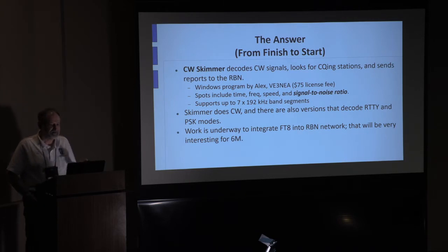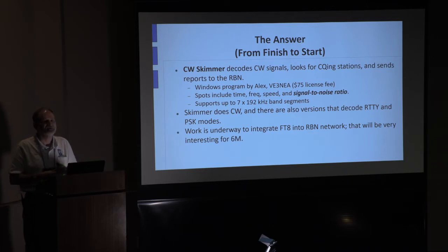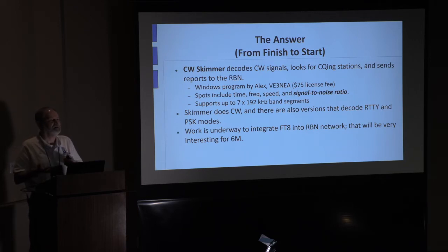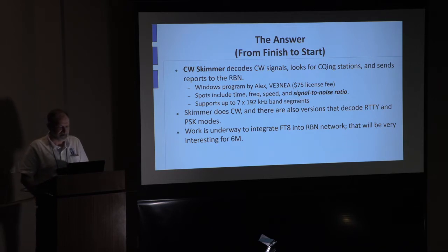So the magic of this is on the HF bands, there's a software called CW Skimmer that can look at a chunk of spectrum coming out of usually an SDR receiver, decode all the CW, pick out the interesting stuff, and format that to be either shown locally as a decoded stream or sent out to the Reverse Beacon Network database.